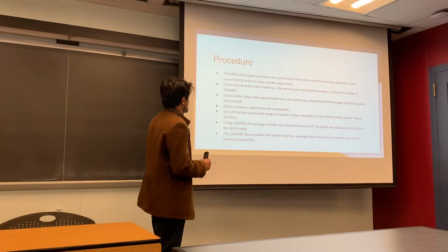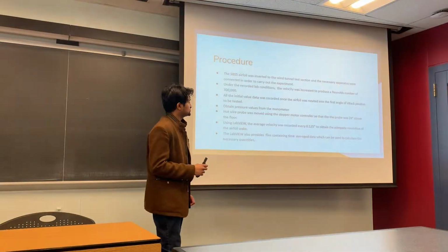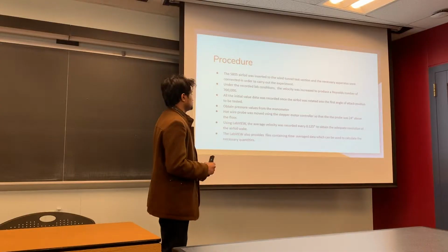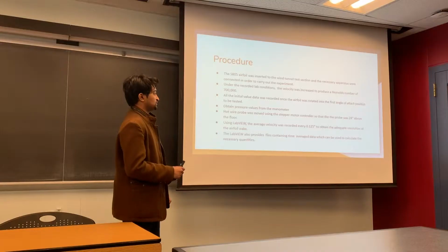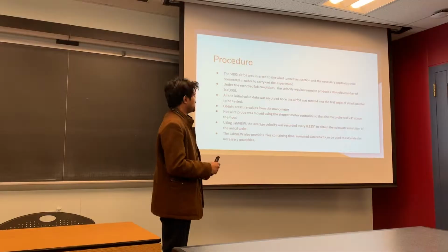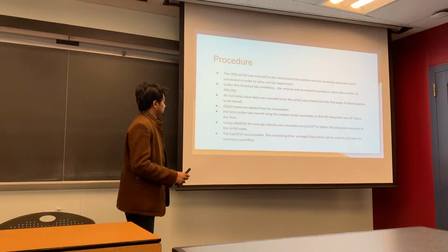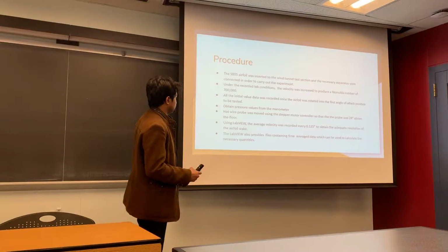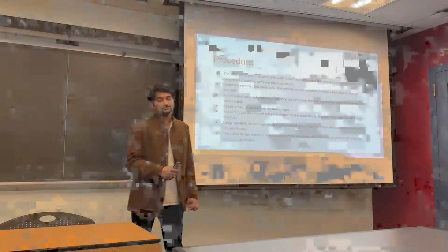After that, the hot wire probe was moved using the stepper motor controller so that the probe was 24 inches above the floor. Using that view, the average velocity was recorded every 0.125 inches to obtain adequate resolution of the airfoil wake. And we also use lab files containing the time average data to calculate the necessary criteria.